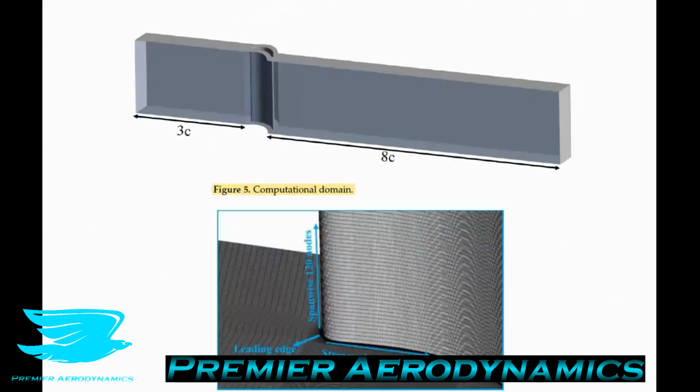So in figure 5, they use a geometric model of the transonic VKI-RG cascade, which is the same as the wind tunnel test model. Since transitional calculations had a high requirement for the mesh refinement of the normal and tangential directions near the wall, the total number of subsequent meshes increased sharply, and the requirements for computing resources were further increased. In other words, because refining this mesh became prohibitively expensive, they only stuck with a certain number of cells, which was 8 million in total.